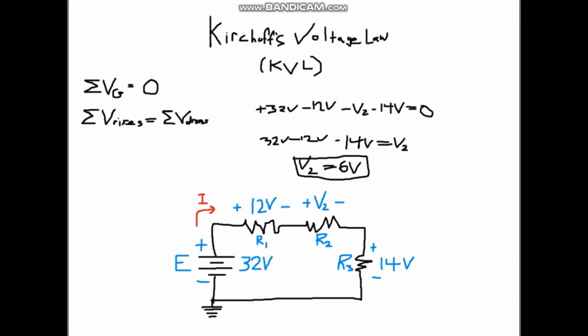If you're taking a circuits course, you're going to use KVL a lot to find unknown voltages, and then it just becomes a starting point. You'll use it for lots of other things, so you'll solve for the voltage and then move on. But KVL is a very important law in circuits, so it's really important that you practice it and get good at using it. So to summarize, essentially you're just going to follow the rises and drops around a loop until you return back to where you started from, and then just solve for the unknown voltage.